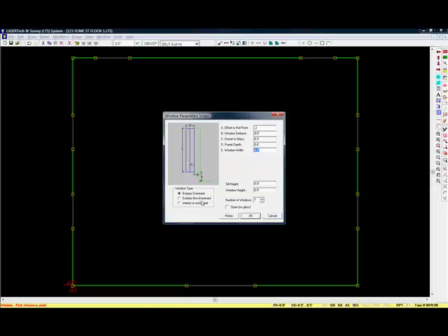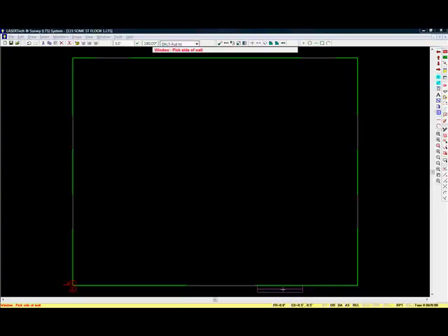So we're going to say this is a dominant exterior window, which our operators will need to know when they're doing BOMA calculations. So there it places the window, and it labels it DOM, D-O-M, and the red line is the glass line. So if we were doing a BOMA calculation, the lease line is going to follow that red line.